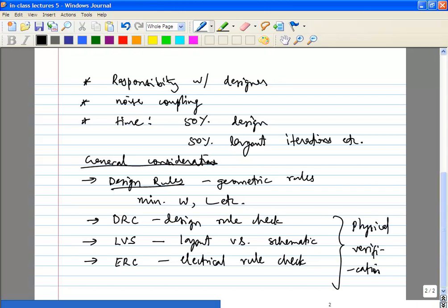Okay, so for example, a lot of modern analog processes or even digital processes have two power supplies. So they'll have what is called a thin oxide transistor. If you take a 65 nanometer process, for example, or a 130 nanometer process, you'll have a transistor whose minimum length is 130 nanometers and its gate oxide thickness is a certain amount, and you'll also have what are called IO transistors.